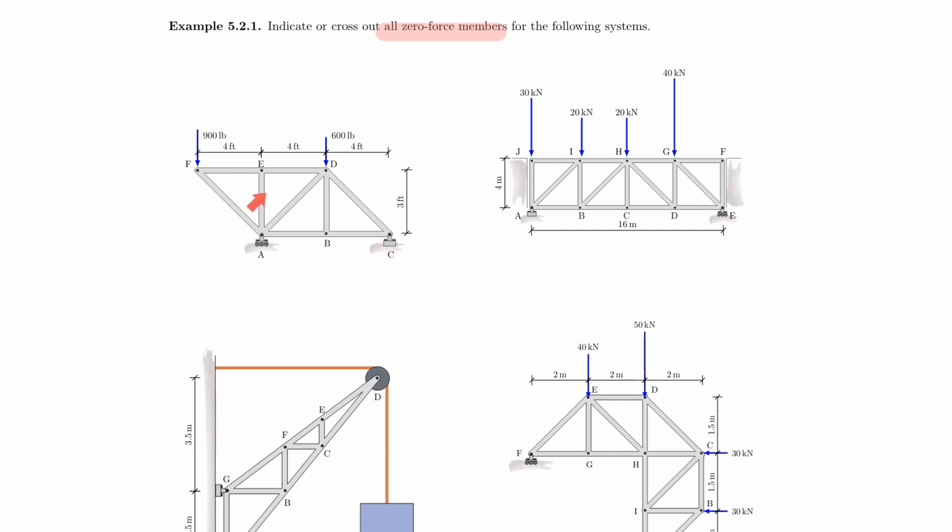So I start here on the top left, and what I see here in node E is 2 parallel ones with a random third one joined. It actually is not random, it's 90 degrees, but the rule is random. And I have the very same effect here at node B. 2 parallel ones and the random third one. So what I can do, and the way I show this, is I cross these out. This is how you would show it on an exam, but for the next ones I just erase them so that you can see what is actually part of the structure.